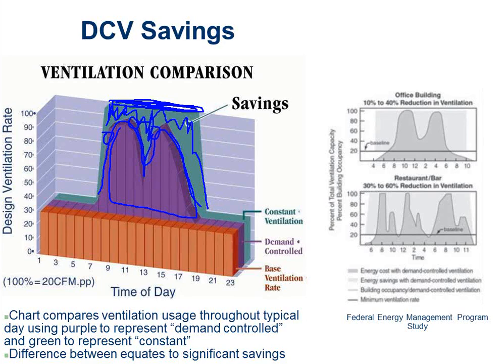But also, we have to ventilate every room for the full design occupancy. Well, when you're all in your offices, no one's in the conference room. Hence, we really don't have to ventilate that conference room if we knew you weren't there with a CO2 sensor. So it's not always necessary that everybody's not there. It's that they're all moving to different rooms, and we only have to ventilate the room that you're in.